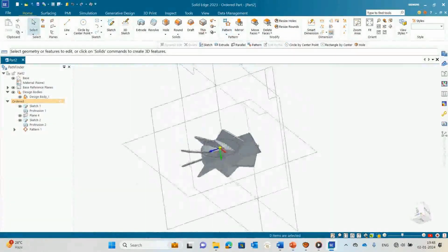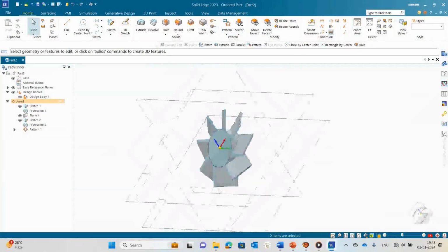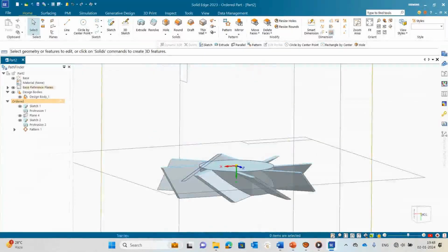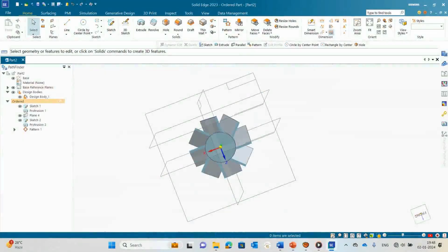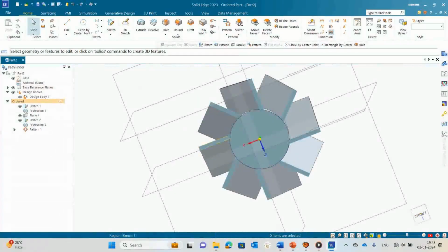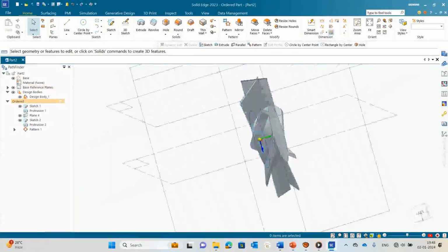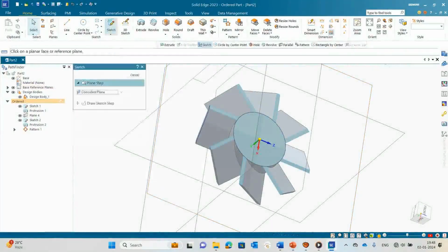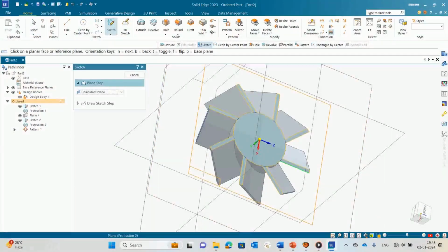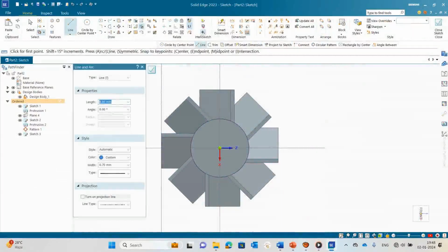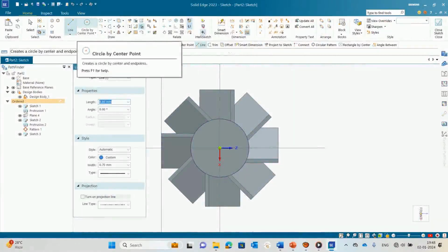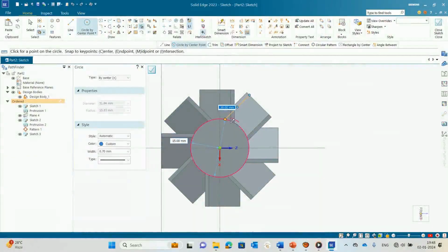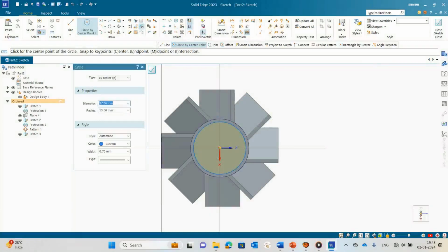So in order to keep it in the proper injector and the combustion liner, we should create the outer and we should cut the inner part also. Now we'll cut the hub. For that we should select the sketch, again with respect to the plane. I will select the corresponding diameter. It's already 30. I will keep around 1.5 mm thickness, so it has to be 27.